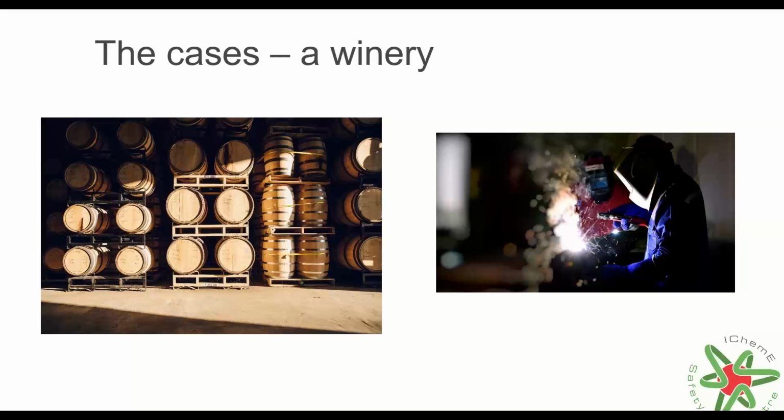checked and there was no effective safe system of work to identify hazards and document controls that needed to be implemented as part of that welding hot work. No atmospheric testing was conducted prior to the welding, nor was the tank positively isolated. So again, what we're seeing here is a change of scope that hasn't been taken into account from when the job was investigated and determined what would be done to when it was actually being undertaken. The circumstances, the environment had changed.